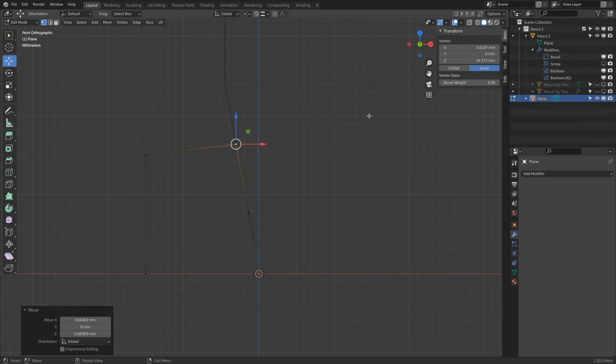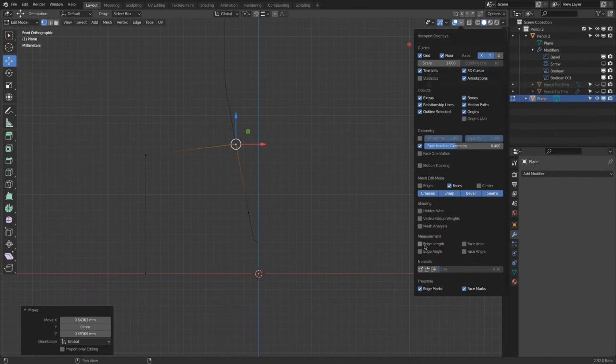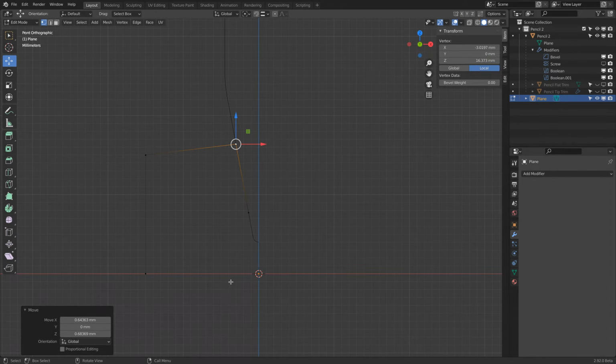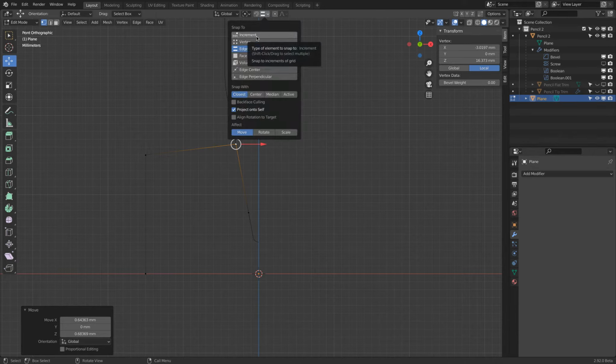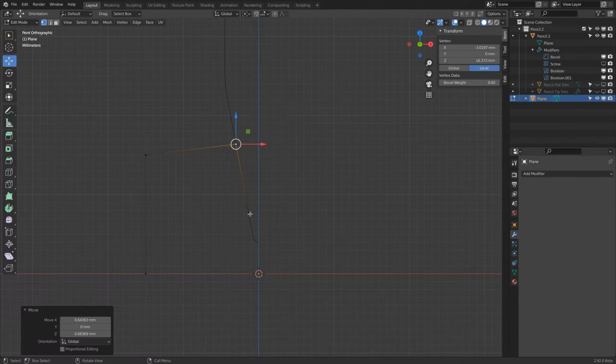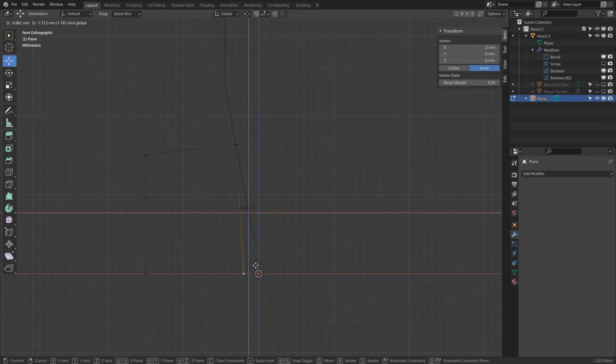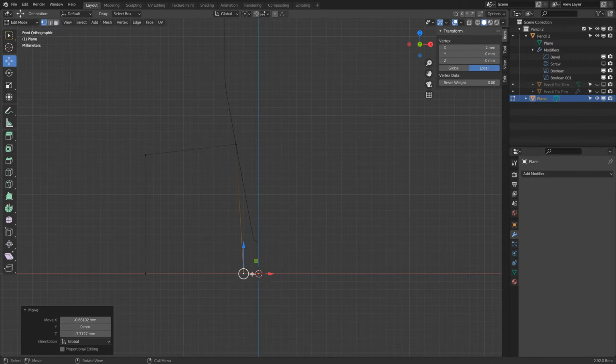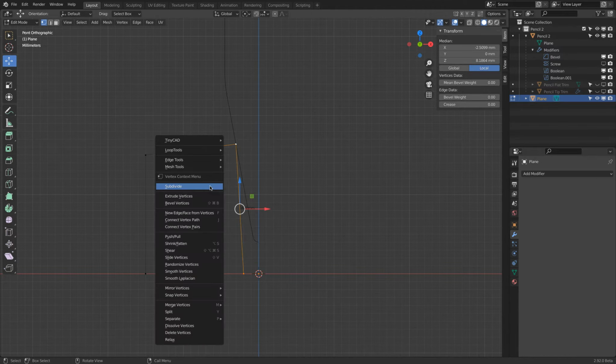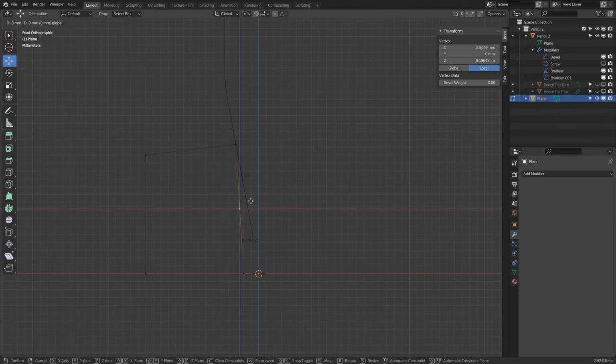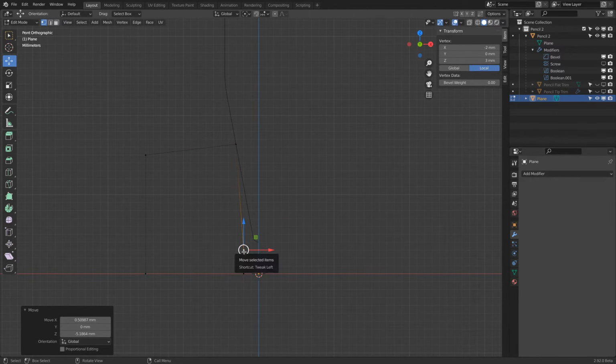And what we now need is really also to pay attention to the dimensions. So we go to overlay, turn edge length on. I would like to have a 2 millimeter distance here for this one to sit on. Let me show you how easy that is to set up. First, we go to snap to grid, absolute grid, select this point, go down, and then I snap here to there. So, because this is 2 millimeters, now I need one more point in between. I select these 2 points, right click, say subdivide, select the midpoint and snap it to somewhere there onto the grid.